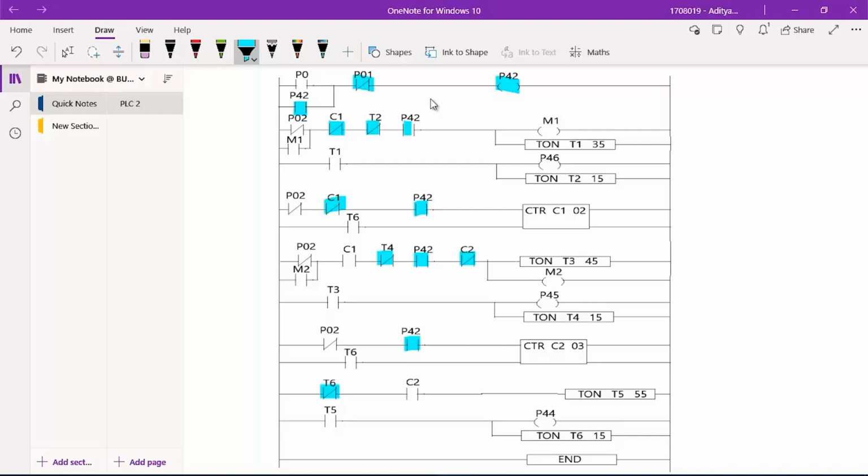Now, if we put an object onto the conveyor belt, it will start moving forward and at a point it will get sensed by the sensor P2. So P2 across this ladder logic diagram will receive signal. As soon as P2 receives signal, this counter C1 will count to 1. This counter C2 will also count to 1.